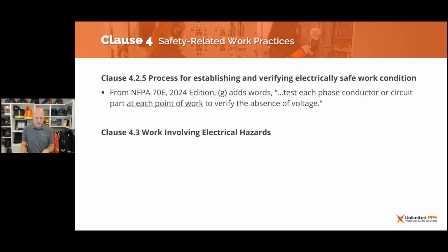Now I've seen from time to time how some employers believe that you can go upstream of a work location and de-energize upstream and then go back to the work location and proceed with your work. However, that is not correct. You need to ensure that at the point of work, the workers that are performing the work are verifying absence of voltage right then and there. They can't go upstream and do it anymore.